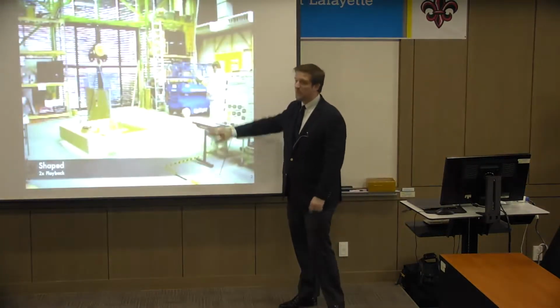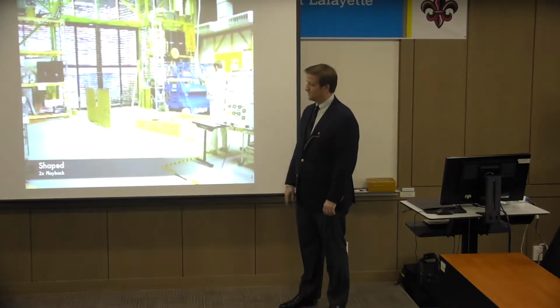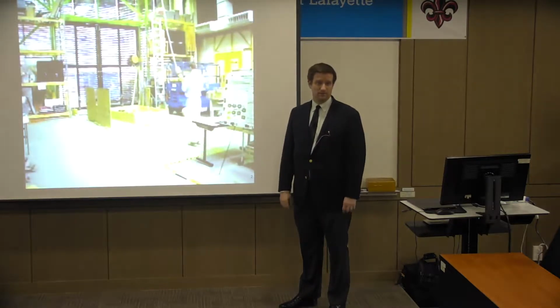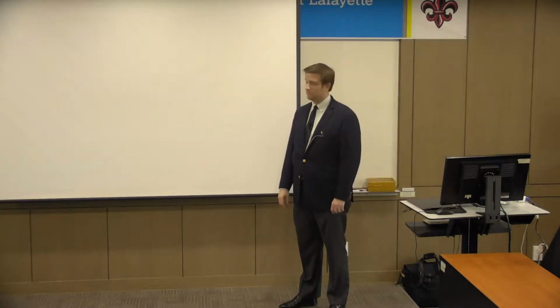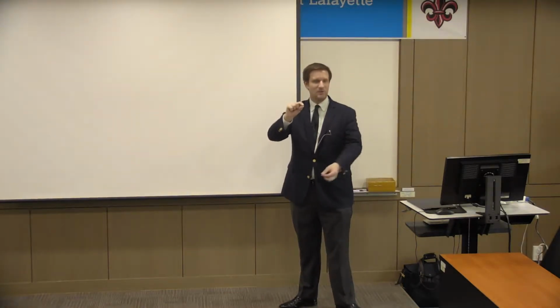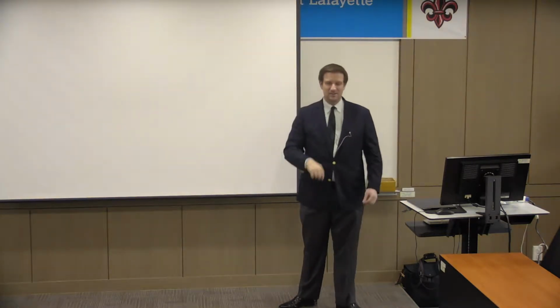So if we can turn on the input shaping instead, we can take the same crane 30 seconds later and move it without any oscillation at all. So this is just a ZV shaper on that crane. So for the crane, we know the natural frequency fairly well, because it's square root of g over L. It's just a pendulum. Right? So we know L pretty easily. We know that frequency with some knowledge.